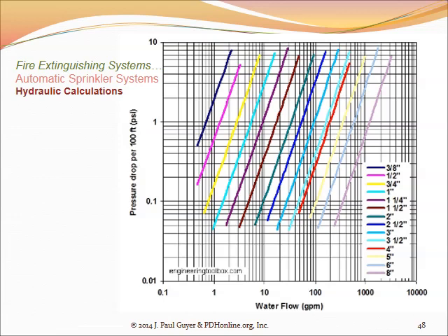And so you just select a pressure drop that will work for your preliminary layout. So you would select, in this simple illustration here, 1 psi of loss due to friction per 100 feet. You can tolerate that with your preliminary layout.